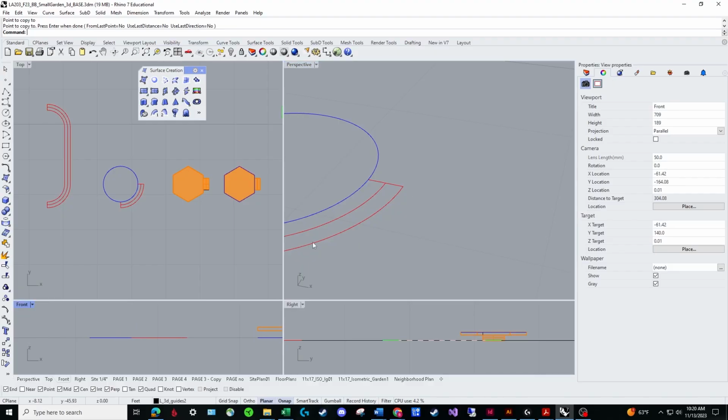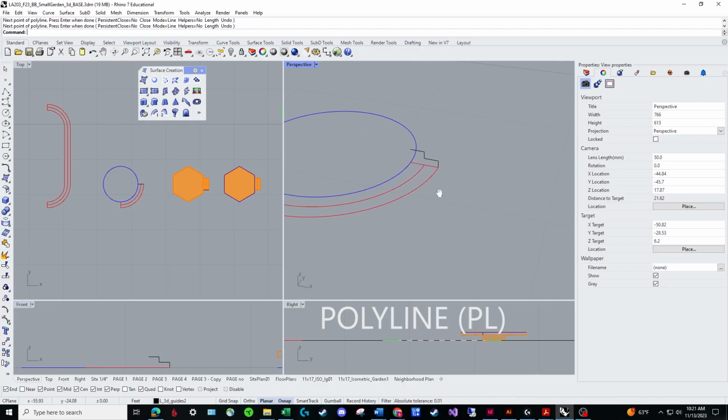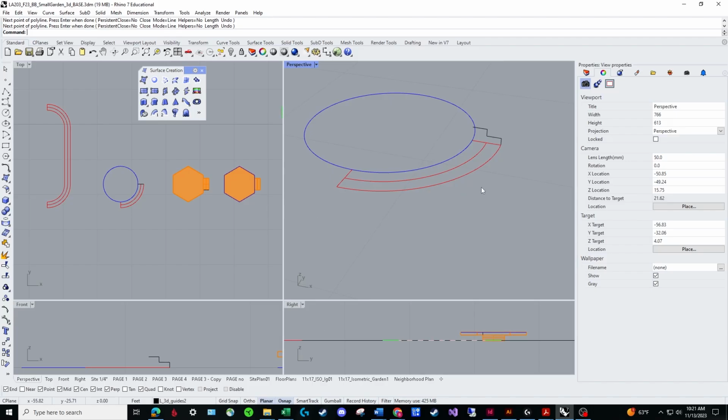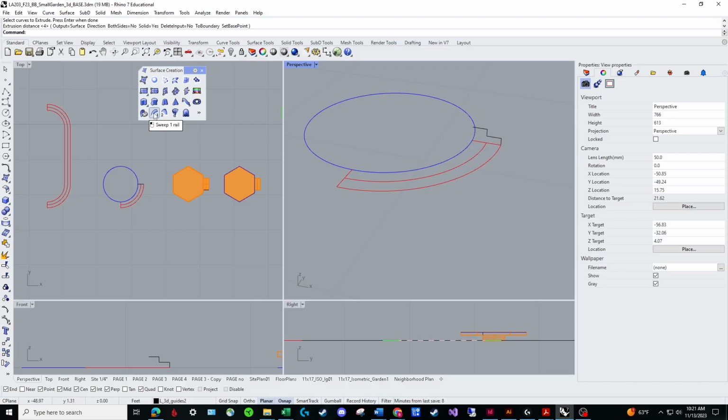If we take another example here, where I'm going to do exactly the same thing I did before, just this 0.5. And get that profile. Here you can see if you're using a rounded surface, you have a little bit of an issue, right, that you can't extrude, because extrude just wants to go rectilinear. It can't make this curve. But this is where the sweep commands come in, because what we can do is essentially sweep this around this surface, or sweep this surface around this geometry.